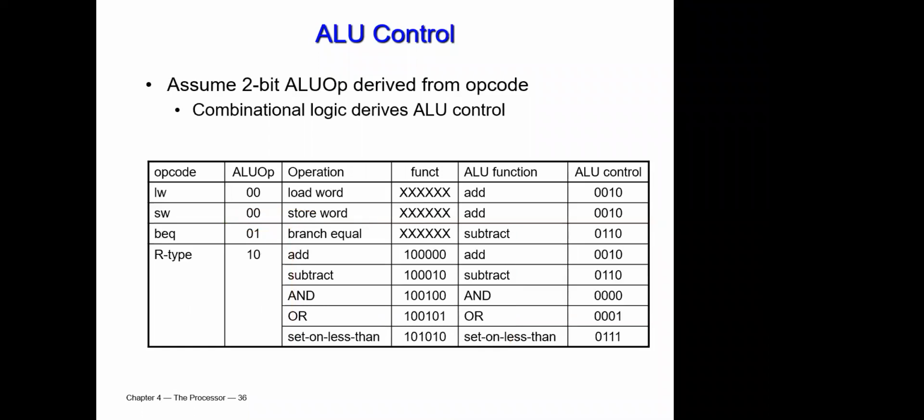But how will we define the ALU control? In another sense, how will I have my ALU control produce this output, not this one or this one? That's why we have something called the ALU op. This will control the ALU operation. First of all, I will read my opcode. If my opcode is load word, my ALU operation will be 0, 0.